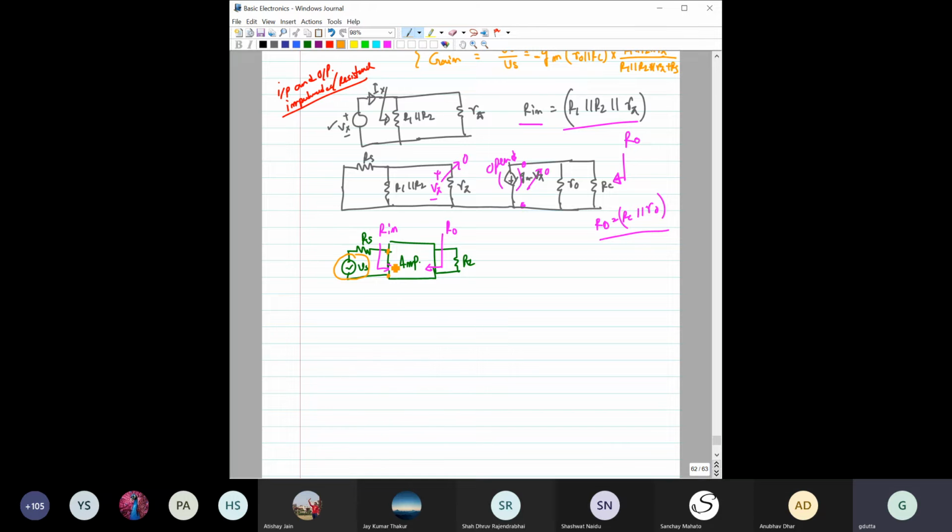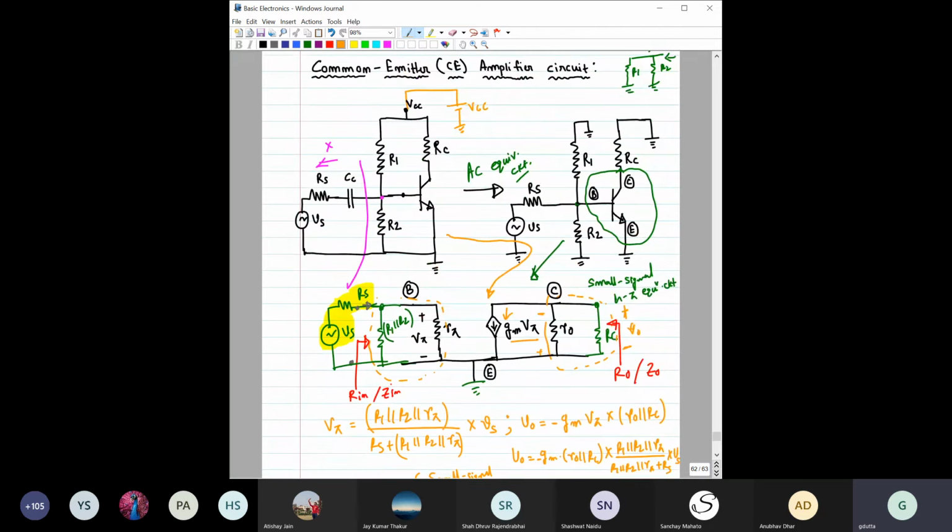That means in the context of a bipolar junction transistor here, what you would like is that the entire VS would drop across this v_BE. Again, small v, small b, small e, right? That's what I'm saying. Because the more signal that appears here, the better would be the amplitude, or the better would be the amplification, right? So you would like the entire signal, if possible, to be dropped across this v_BE. For that, what should happen?